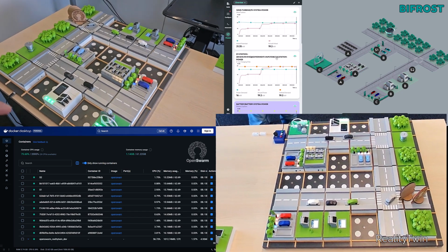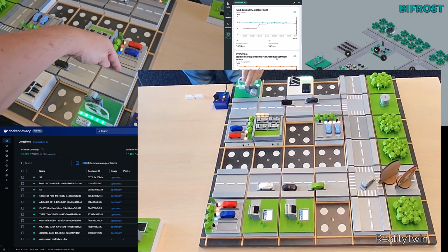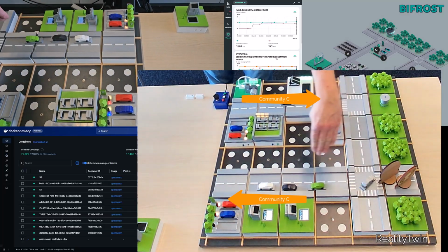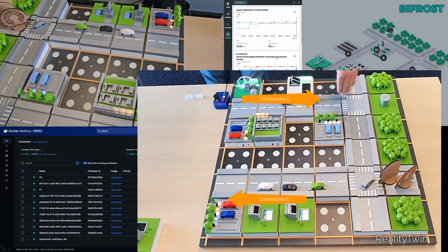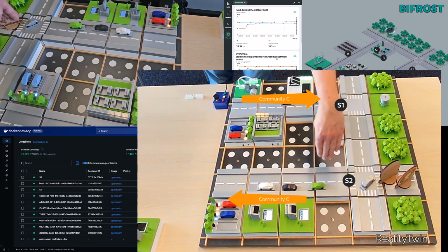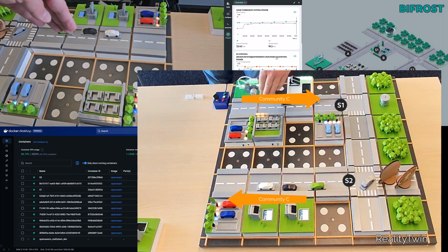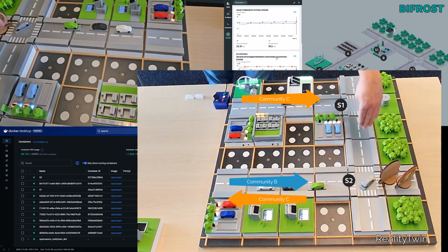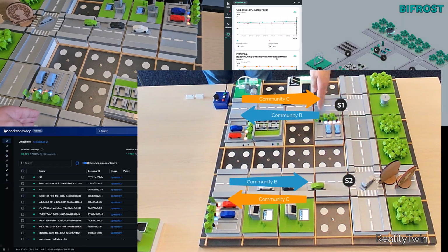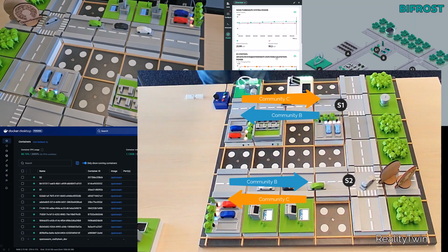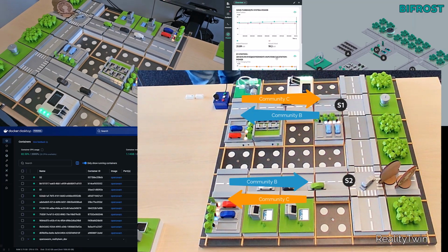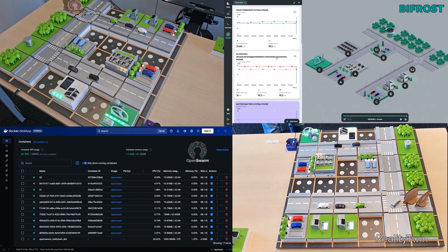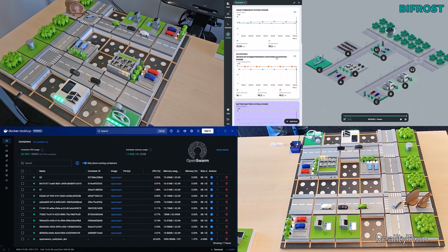We have a generation here and demand here at this feeder, going over sensor 1 and sensor 2. But we now also have feed-in from this side over sensor 2 to sensor 1 and to this charging station. So the controller can now see there is a cancellation in load flows.